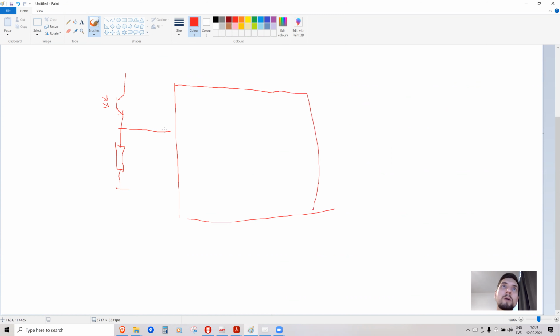This microcontroller has a small RC filter built in. You can enable it, and if you disable it, then there's a transistor which basically connects the input directly. So this is a bypass thing. So we want to enable this internal RC filter to improve our analog signal a little bit.